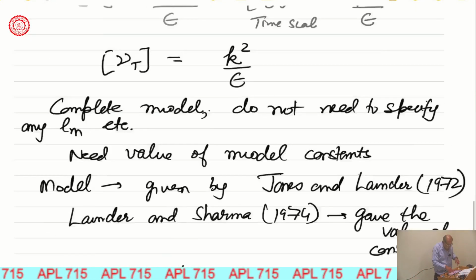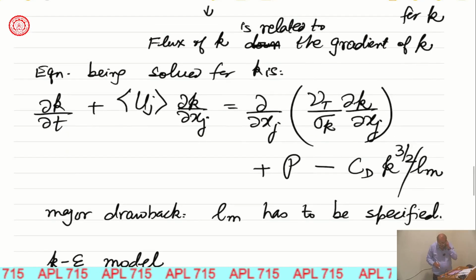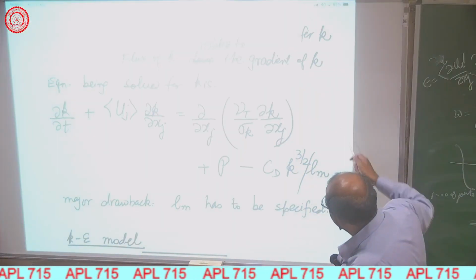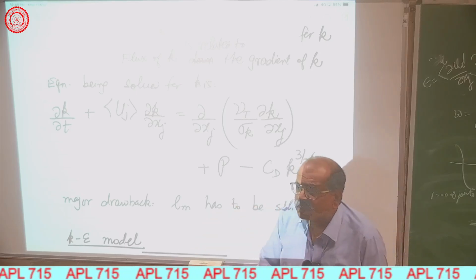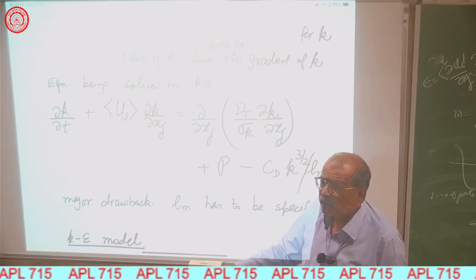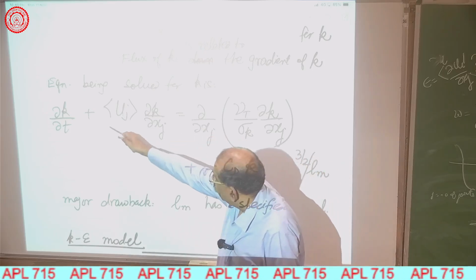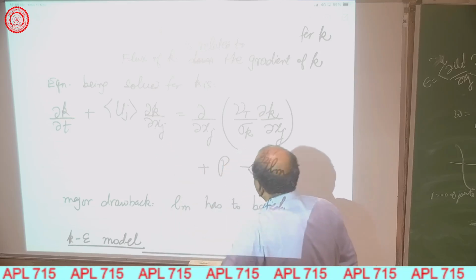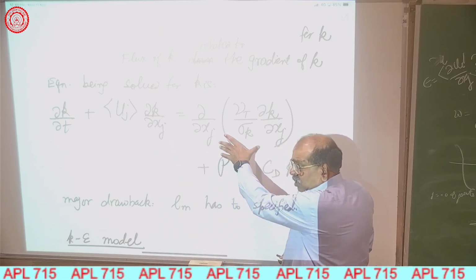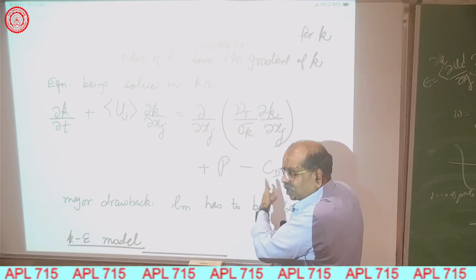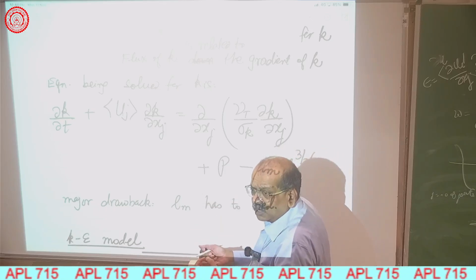So what we do, as modelers or as people in the community, is we try to look at equations of all the quantities. And as he said, all of them have the same form. You look at the equation for mean velocity, it has exactly this form with k replaced by mean velocity and this term being replaced by the new laminar term. Then if there's a pressure term or something, whatever is causing that.